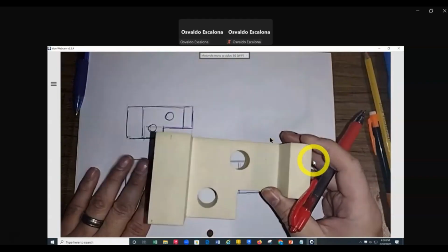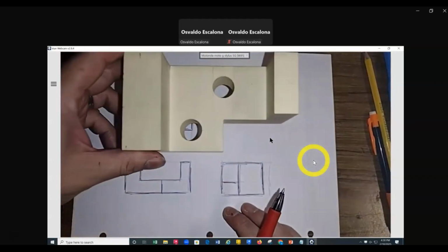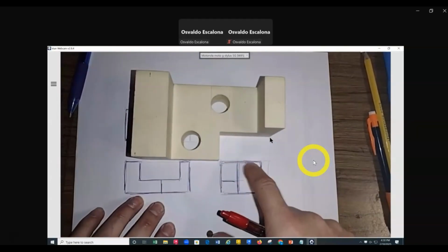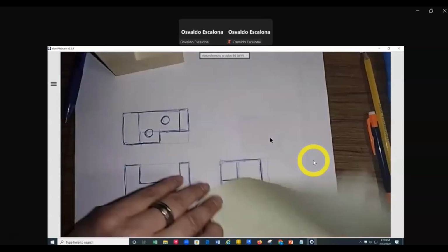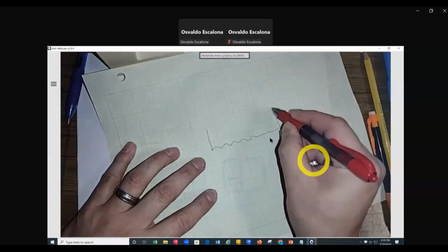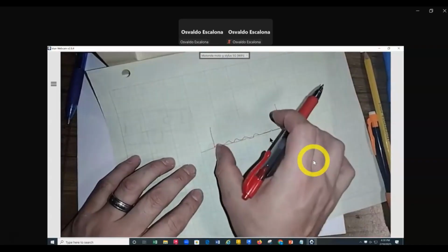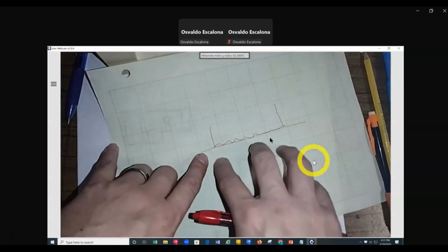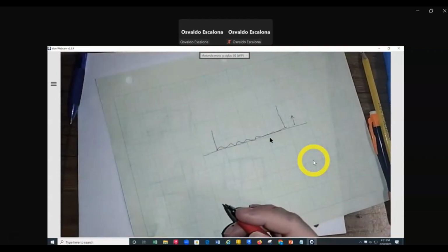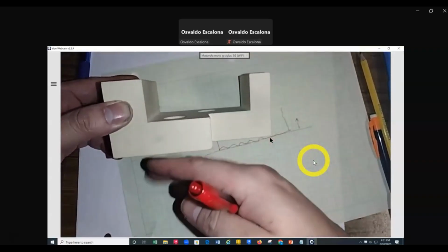Right? So let's say that I come and I say, this block is going to sit on top of something. This is my datum. Not my part itself. It is what it is made into. For example, my part will be imperfect. If I were to look at the bottom of the part, it might look like this. Yes? But what I care about is that once it sits on the table, that is the bottom of it. And I dimension from there, most likely, I don't know, it depends on the function in reality, right? But it goes from the bottom to the top. You see? From the bottom to the top.